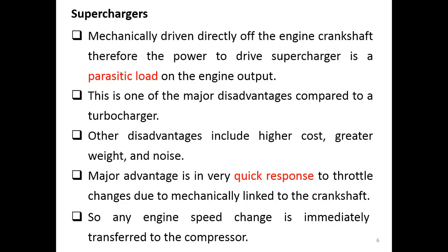Now, when we talk about the throttle change, it always refers to the loading that happens to the engines. So this supercharger gives you a quick, or fast, response because it is mechanically linked directly to the crankshaft of the engine. So whatever happens to the engine, the supercharger also feels it.